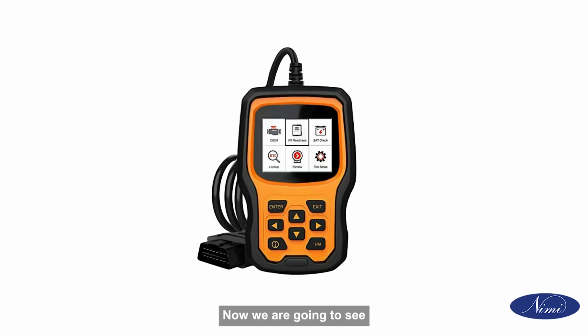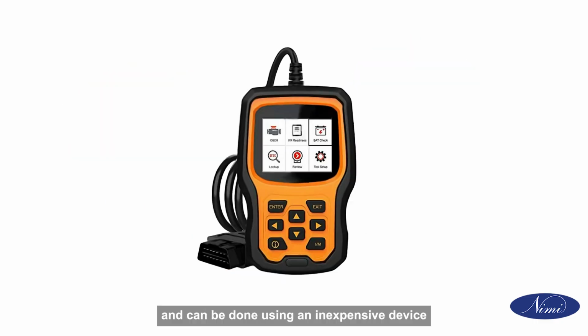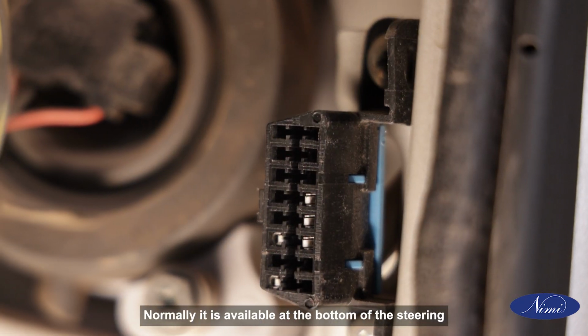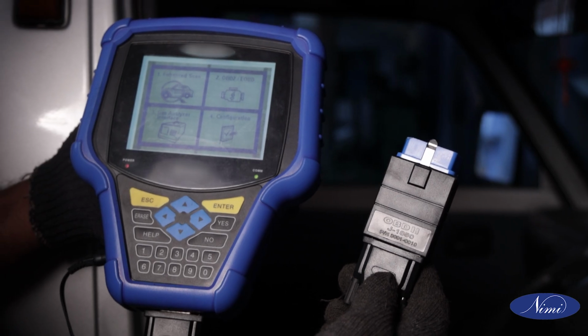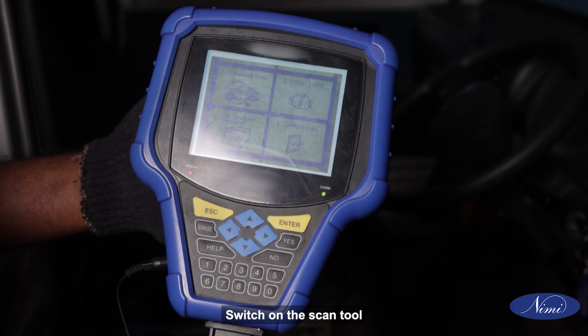Now, we are going to see how to scan the engine ECM. This is useful because it allows us to see if there are any problems with the engine that need fixing. It is not very difficult and can be done using an inexpensive device, which we will also discuss here. Identify the data link connector in the vehicle. Normally, it is available at the bottom of the steering. Connect the scan tool to the data link connector. Switch the ignition on and switch on the scan tool.